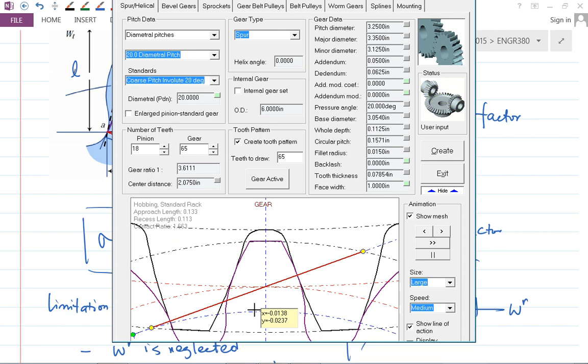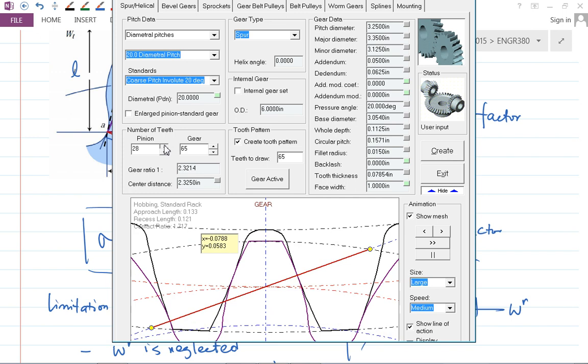So you basically can draw a tangent line up to this location, right? And you can find x by drawing a perpendicular, right? So then what happens if I increase the pinion number? Watch the tooth form. Look at the bottom there. And then what happened? It's thicker, right? Or in other words, the tooth profile becomes more like a straight line, right? More like a straight line.